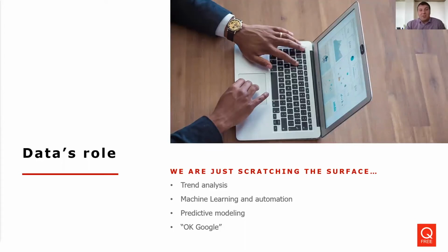With all that data too, and all these different technologies, we can build in machine learning, automation. So if a traffic technician or engineer corrects a problem or manages an incident, the system's actually recording all that and essentially learning that behavior, right? And with that too, it's learning behavior of traffic out in the field. So on the freeway, if the traffic congestion is matching a certain model that's resulted in an accident 4 out of 5 times, then it can predict it and say, look, we're approaching the same type of congestion model. We're probably going to have an accident. We need to do something to mitigate this problem.